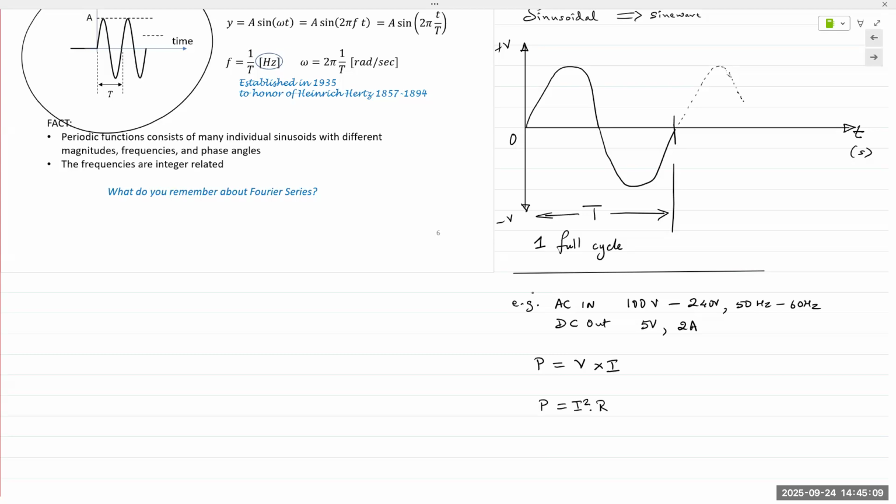So when you want to have a hot tub installed, a hot tub requires huge amounts of power, which is not possible because it exceeds the residential power rating. You have to heat up a large quantity of water, plus you have these jets and pumps. And so to increase the power, the electrician will come out, obtain a license from the county or the local government, and run 2 lines, 120 volts in series with 120 volts.